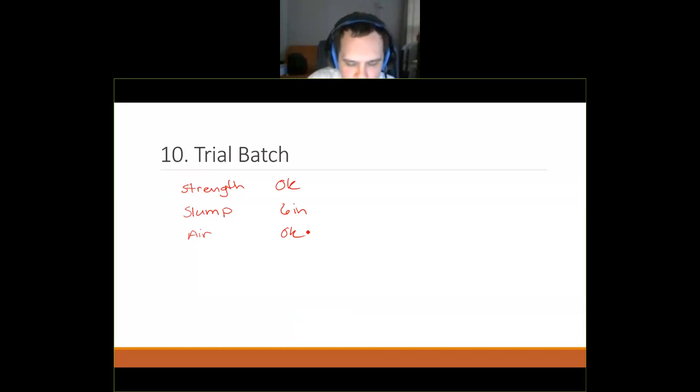And what we had said in the lecture, if we want to adjust our slump, it's going to be 1 inch of slump is roughly equivalent to 10 pounds per cubic yard of concrete. All right. Now, in this mixture, we had started with 295 pounds per cubic yard. Okay. Now, it's important that you keep these units consistent.